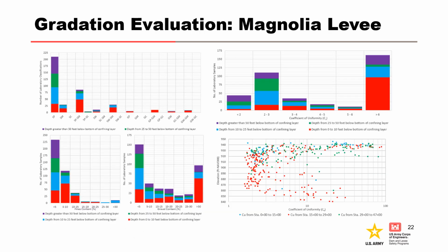It is also essential to properly classify the soils according to the Unified Soil Classification System, or USCS, using ASTM standard D2488. This requires a critical review of historic data and possible reclassification as part of the site characterization.